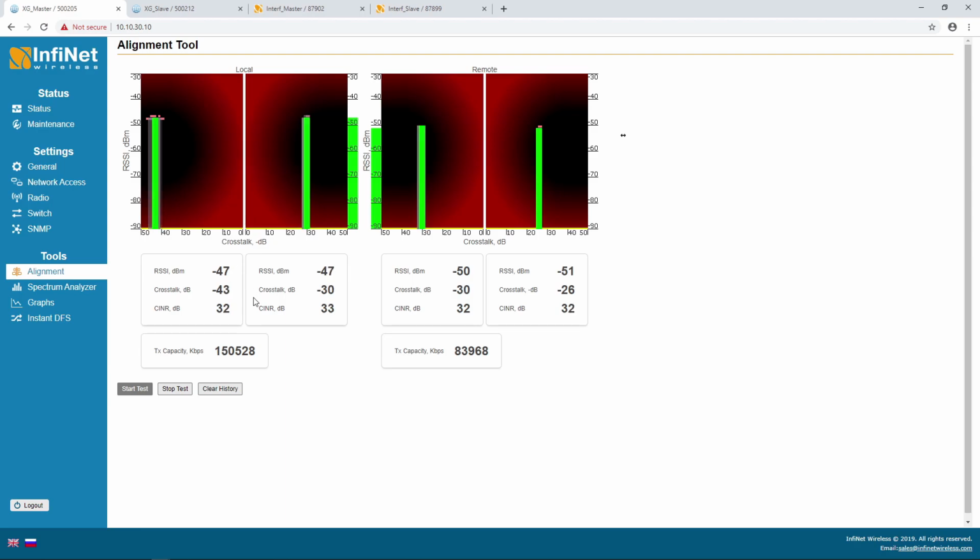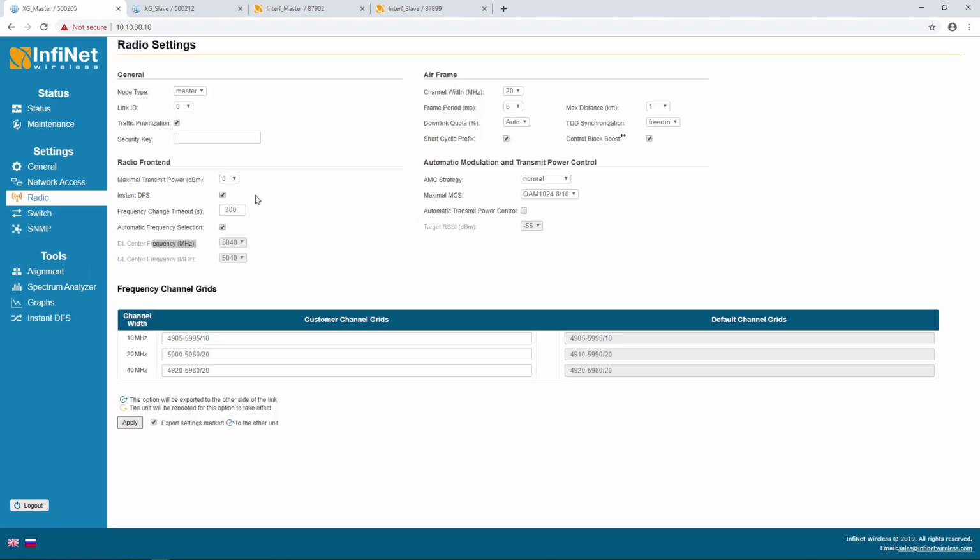The last aspect that I want to show you regarding the troubleshooting for the configuration of the device are the radio settings. Here we have some parameters that influence the throughput, as we already discussed, the channel width, and you have here the available options that should be present in the license file as well.